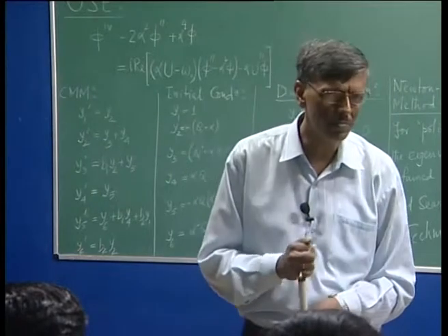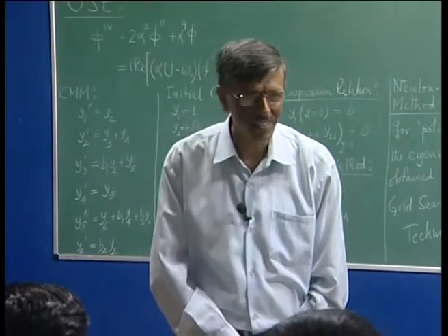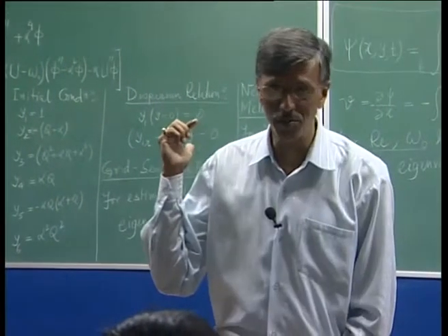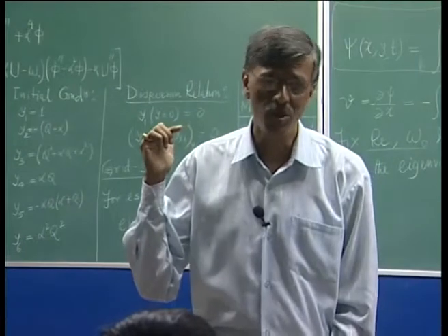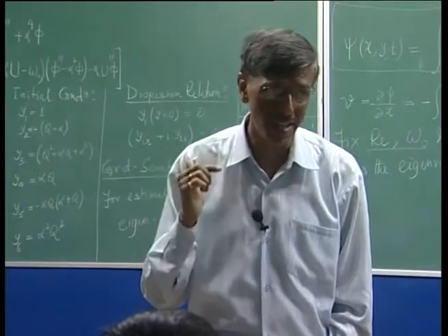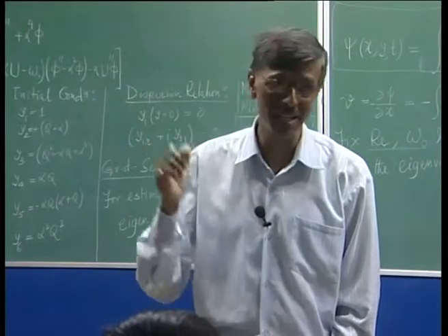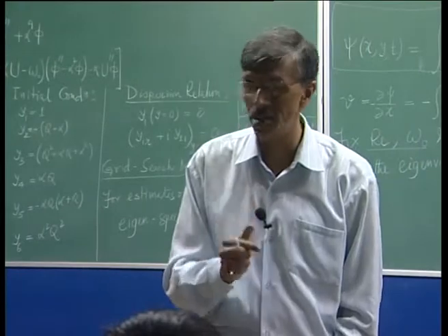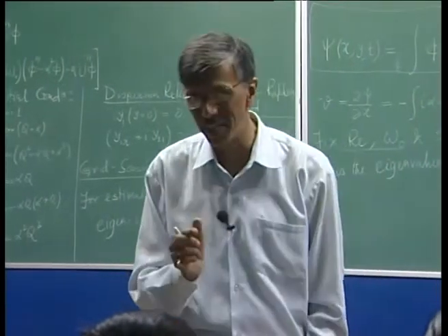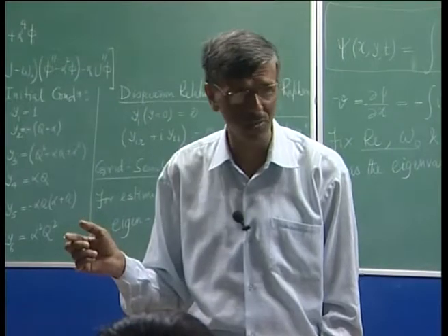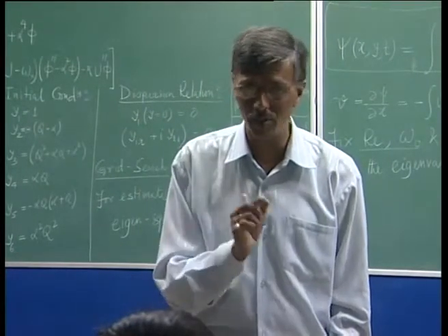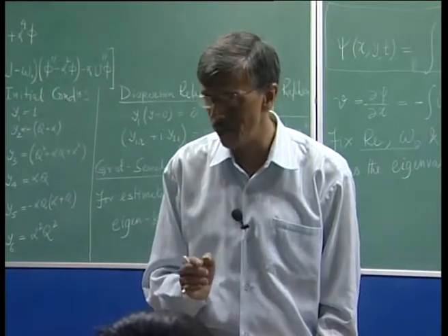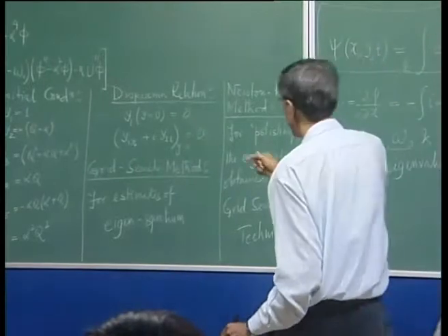We have got to understand it because we have already seen that this is not an ODE. The Orr-Sommerfeld equation is an ODE. Why? Because we are looking in the wave number plane, so that space dependence has been masked there. So, it is not simply an ordinary differential equation. If it was an ordinary differential equation, then giving omega naught and expecting omega naught in the response field is perfectly justified, but we have a space-time dependence of the problem. And in a space-time dependent problem, we have what we call here the dispersion relation.